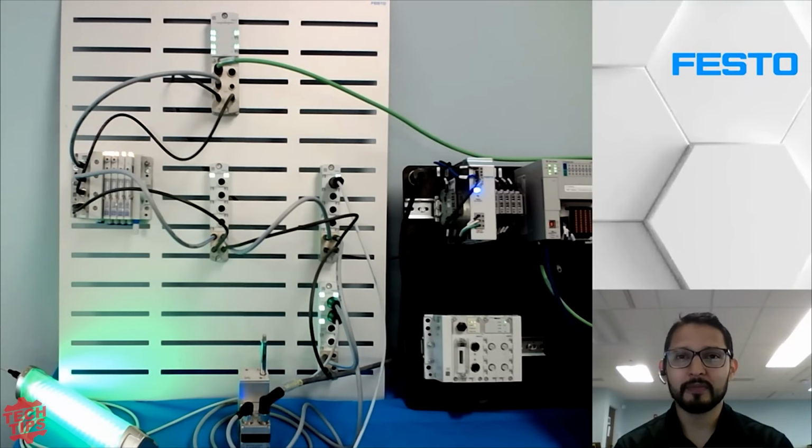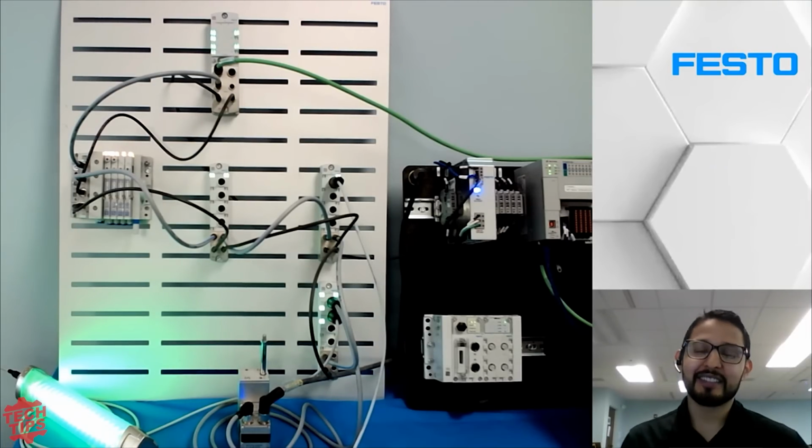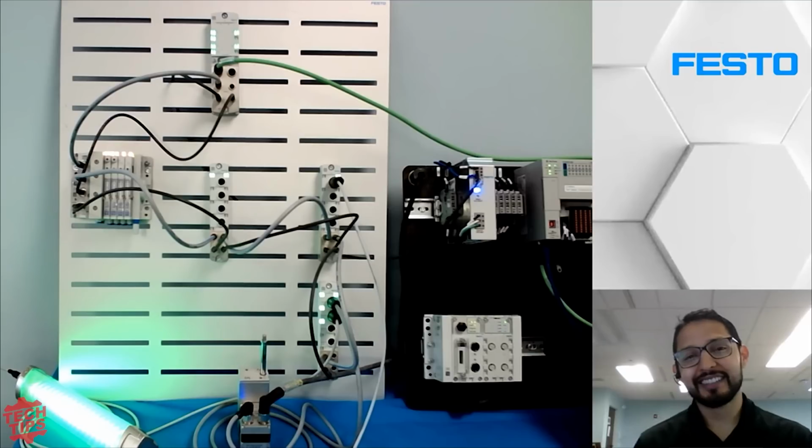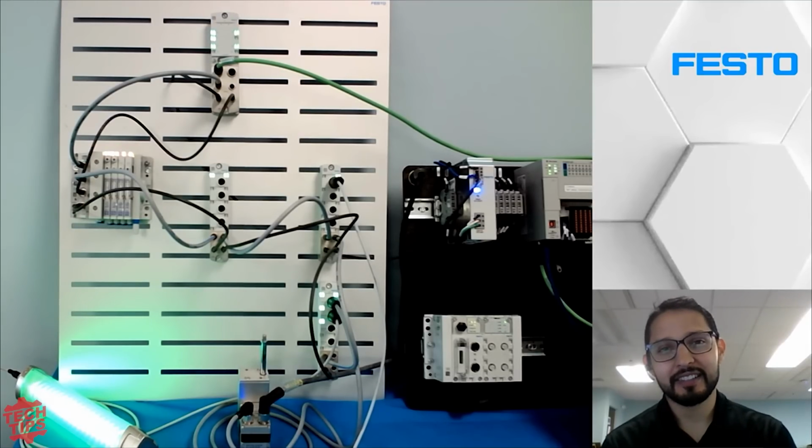And I mean, what you would normally have to do manually, you're getting the item added to the IO tree as the right address and the right instances and assemblies and all that. You're also getting the code needed to read and write things, right? Because you have to do a read, you have to do a write. But finally, you're also getting UDTs, and those UDTs are fully documented based on your configuration. So it really does, in that one export, give you what would typically take an hour or two to put together, very labor intensive, trying to document everything and whatnot.